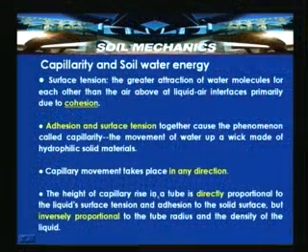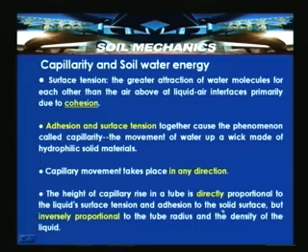The height of the capillary rise in a tube is directly proportional to the liquid surface tension and the adhesion to the solid surface, which is very important, but inversely proportional to the tube radius or diameter and the density of the liquid. Inversely proportional to the density of the liquid, because in the derivation we have discussed the density which is in the denominator. So, inversely proportional to the density and to the diameter.